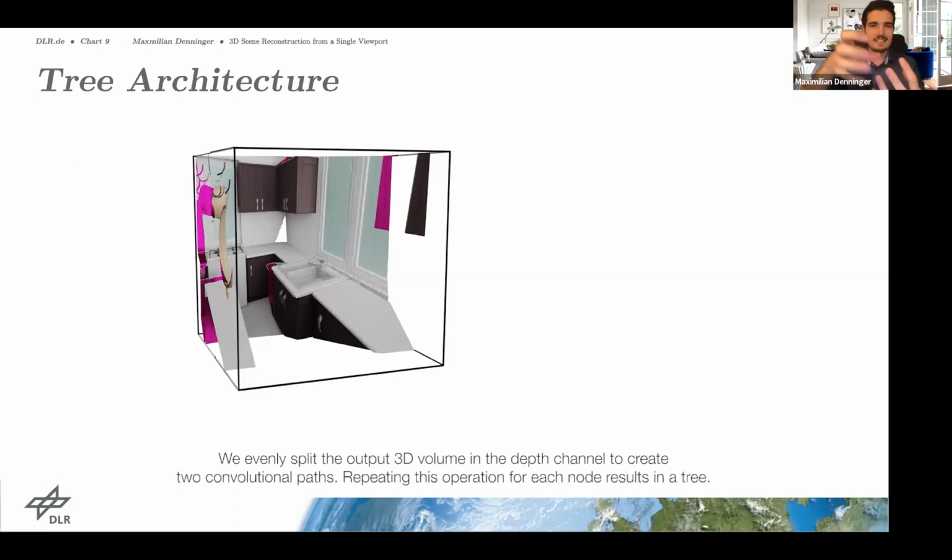The problem is it's not really easy to incorporate into this idea we had for this approach, where we wanted to reconstruct a scene completely. You could convert your depth image, which you could get from a stereo sensor or whatever sensor you use, into a point cloud, and then try to fill in the voids. What we discovered is that sometimes this doesn't work really well, especially to fill in gaps, because it's unsure about the direction of the camera in the scene, because you lost that information while transferring it to a point cloud, which is usually really important.